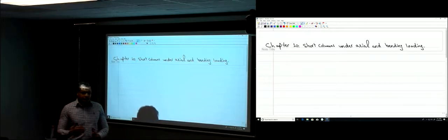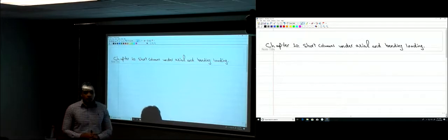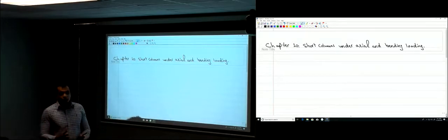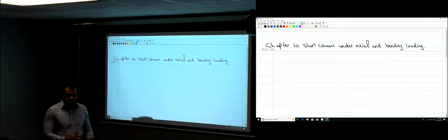No, you cannot design for bending moment and for normal or axial force independently. Why? They act together. Shear acts together with bending. When you have bending moment, you have shear. They come together, right? But the type of stresses are different.